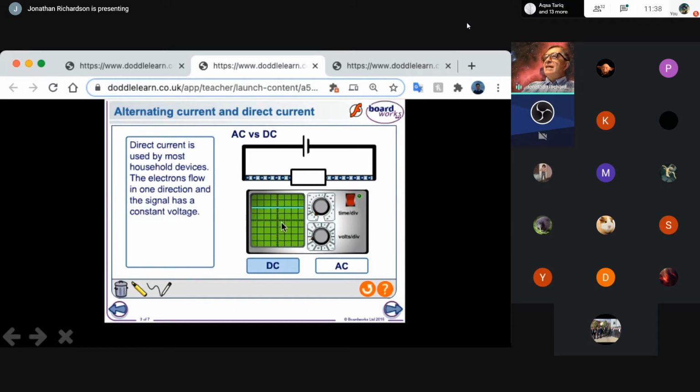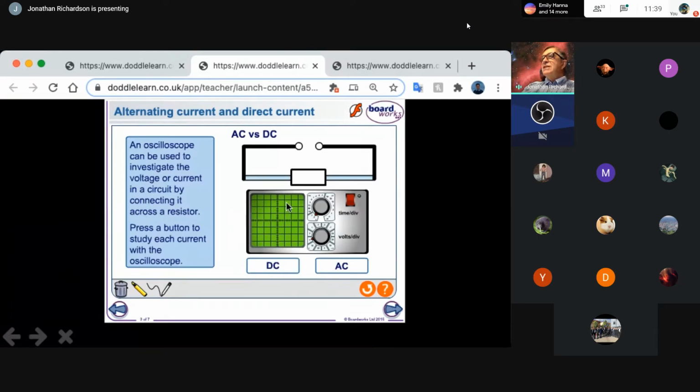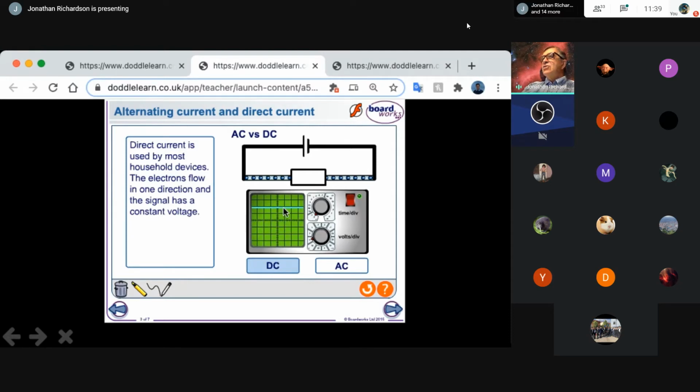And what you can see on this oscilloscope just here is, if you look at the scale, let's just say every one of these squares vertically is a measure of 1 volt. Now, I don't think I can change the circuit here, no. But if I turn this off, you'll see that the voltage disappears. Turn it on and the voltage goes from this 0 level at the center to 1, 2 volts.